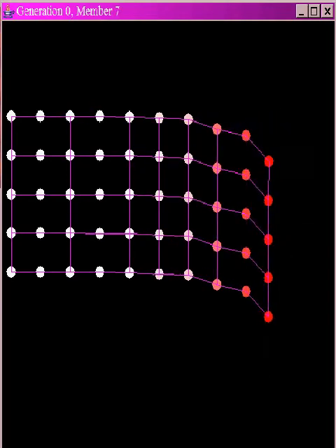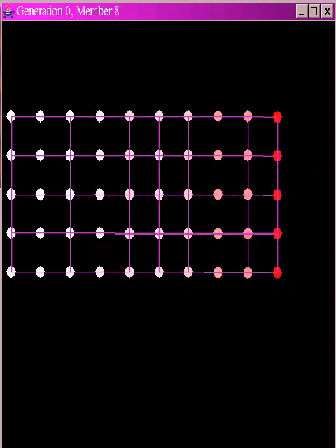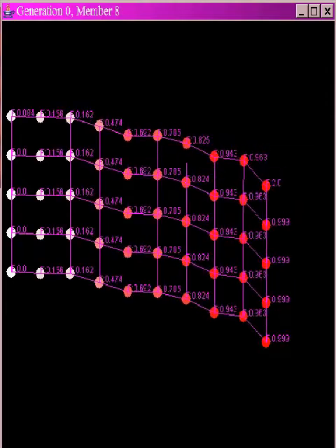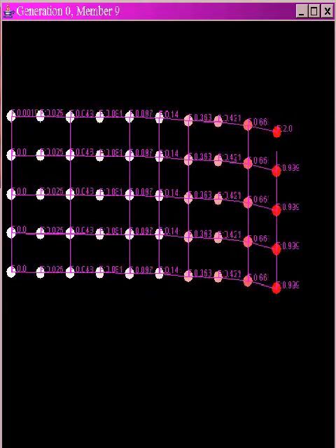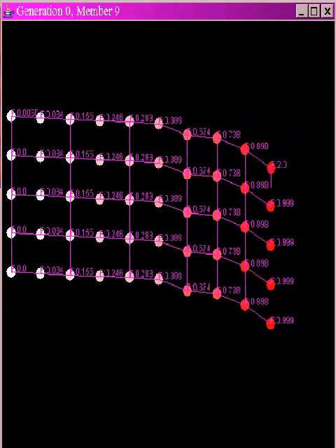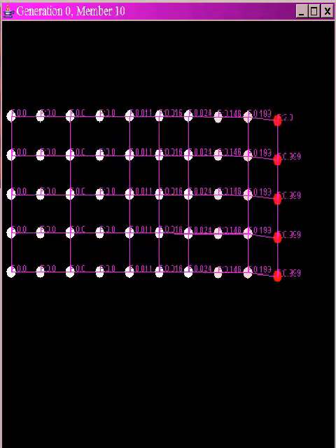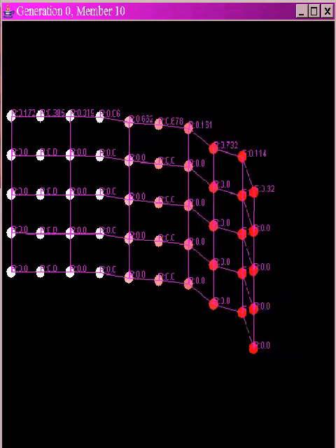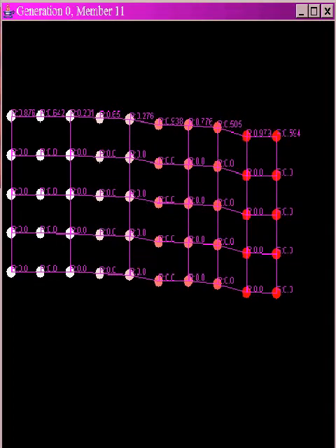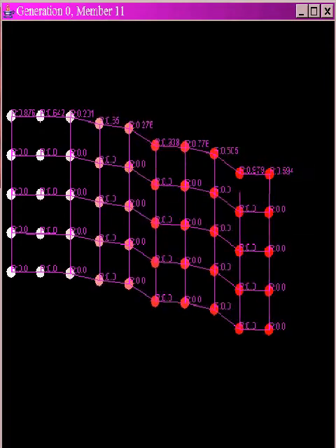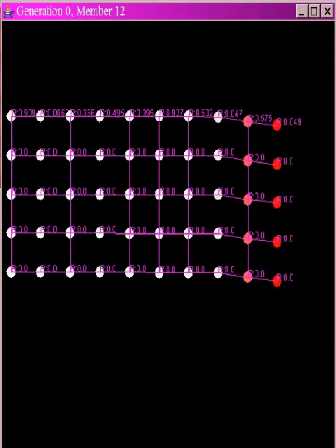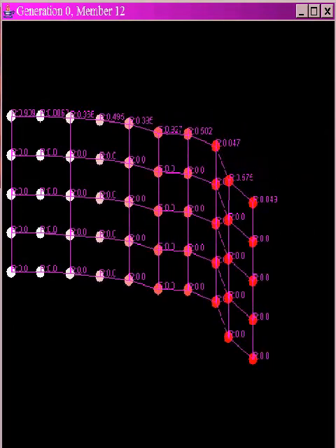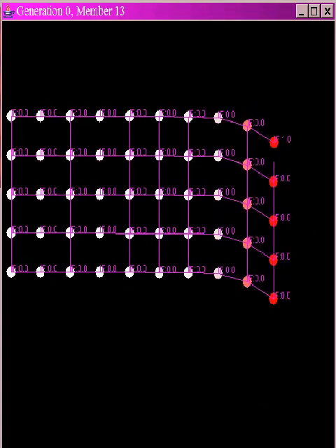After each individual is measured, the 5 most fit members are mated by selecting, rod by rod, a new rigidity for the offspring, randomly picked to be somewhere between the corresponding rigidity of each parent's rods. This results in 25 new individuals, which will include the 5 most fit individuals, resulting from each one mating with itself. 5 new random members are also generated, resulting in a new population of 30 individuals. A 2% mutation rate is applied to all matings. As can be seen, randomly generated materials do not generally exhibit the desired linear response.